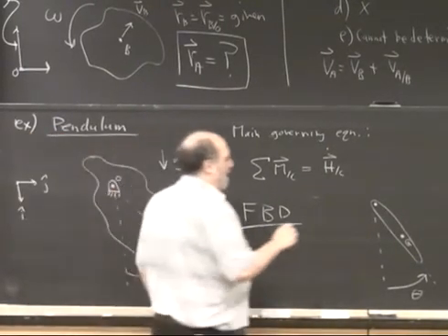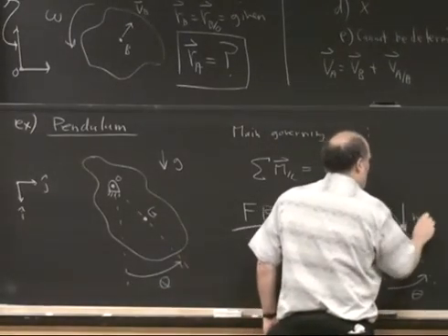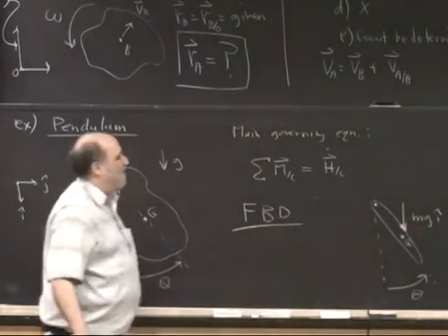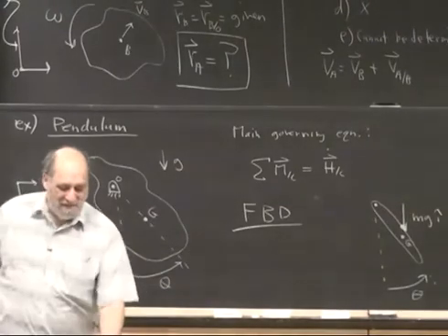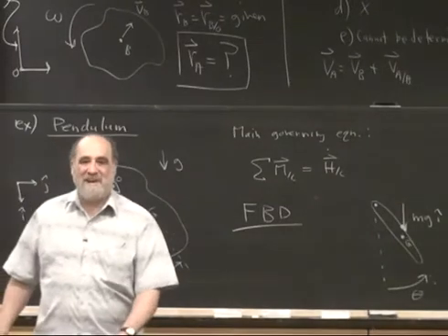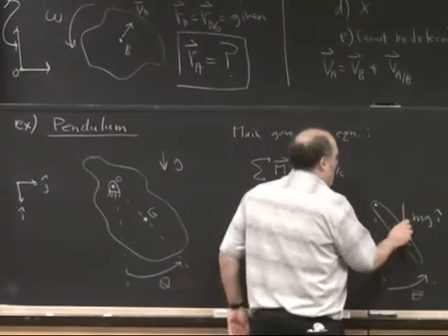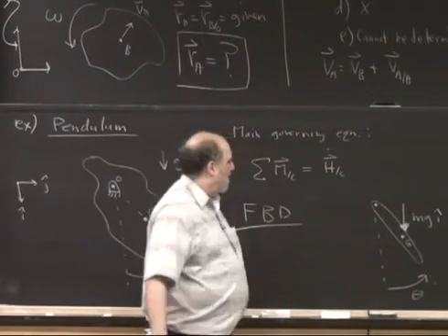Okay, so we have acting on this thing gravity force. And we can put mgi here, or give it mg and have it implicit that it's times a unit vector in that direction. For a rigid object, gravity forces are statically equivalent, dynamically equivalent, equipollent, the same as, for all dynamics purposes, a single force at the center of mass. So for a given free body diagram in a constant gravitational field, you can replace the gravity forces with a single force at the center of mass.